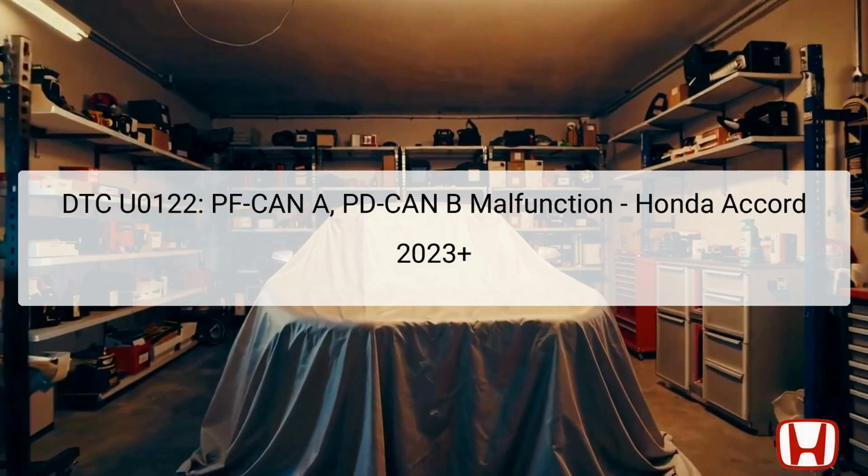When the PCM is unable to receive signals from the VSA modulator-control unit, either the communication lines are faulty or the unit itself may have issues. The root cause could also be related to power or ground circuit failures. To effectively address this issue, a thorough understanding of these components' locations and roles is essential, along with a methodical approach to troubleshooting, ensuring that any underlying electrical issues are resolved.